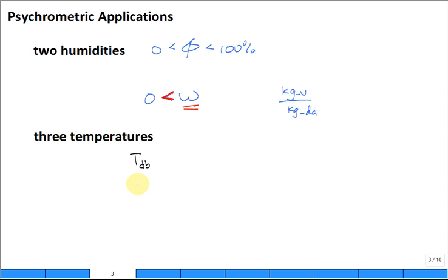All right. The next temperature was the dew point. True? The dew point temperature. And so for moist air, you do have two temperatures describing its condition: its dry bulb temperature and the dew point temperature. Now, that dew point temperature is going to be less than the dry bulb. That's a kind of tricky concept. And it can be equal to the dry bulb if it's saturated air. If it's saturated air, the current temperature is the dew point temperature, because if you cool it any more, it's going to dew out.